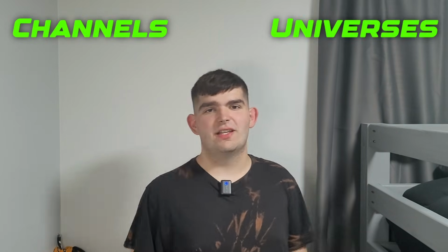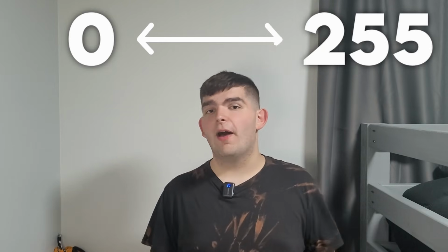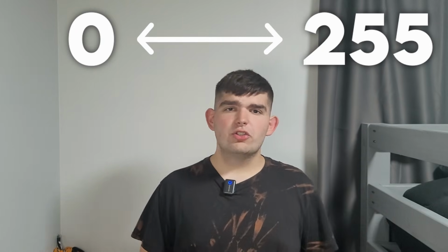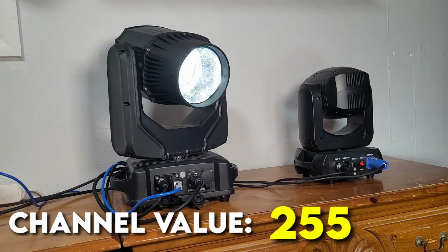The reason why is because DMX uses channels and universes, and a lot of you are probably already familiar with what those are. A DMX channel controls a single aspect or a single parameter of a special effect device. Let's say if it's a moving head, that one channel could control the brightness of the LED, or it could control how much it should rotate, or what color the light should be. The channel can be set to a value between 0 and 255 to change what the parameter does. So if it's affecting the brightness of a light, 0 could mean the light's completely off, but putting it up to 255 could put the light at maximum brightness.